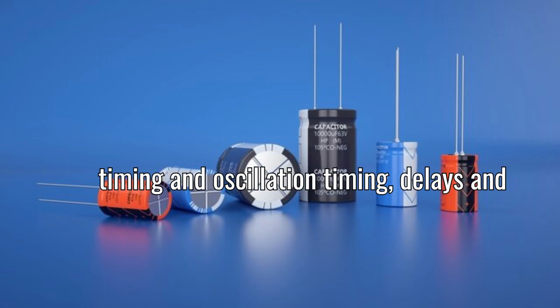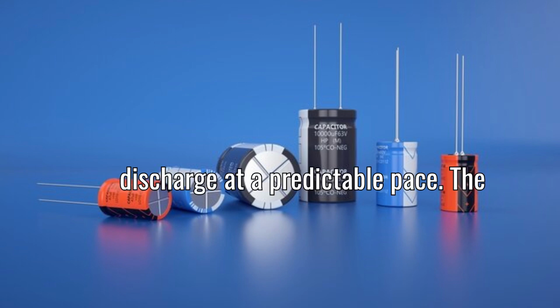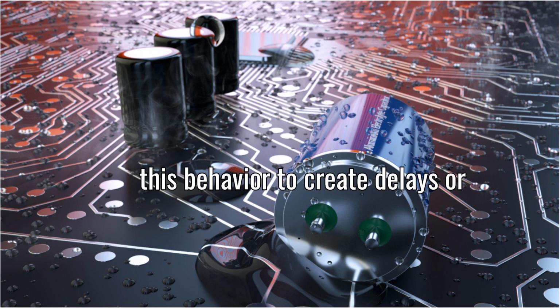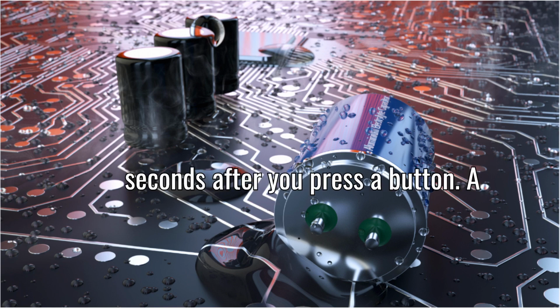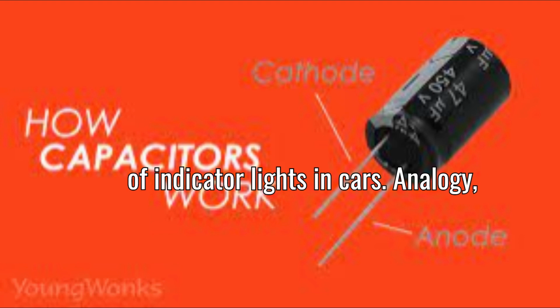Number 5 is timing and oscillation. Timing, delays and intervals. A capacitor can charge up and discharge at a predictable pace. The bigger the capacitor, the longer it takes to charge or discharge. Circuits use this behavior to create delays or specific time intervals. Examples: an automatic light that stays on for 10 seconds after you press a button, a washing machine cycle timer, the blinking of indicator lights in cars.